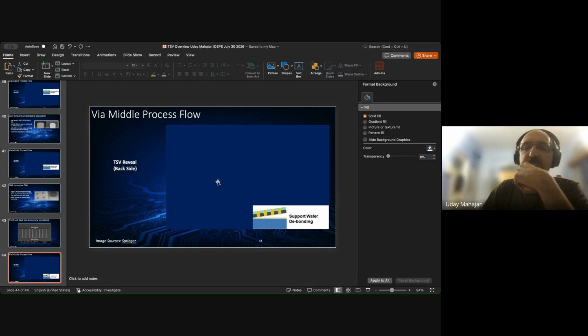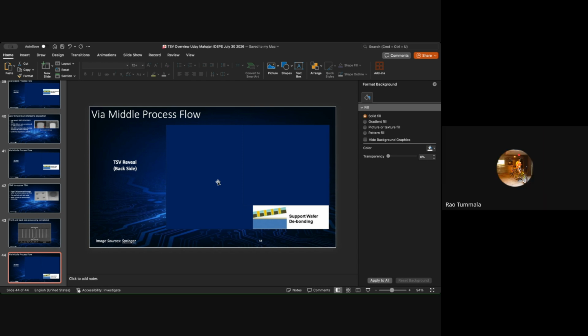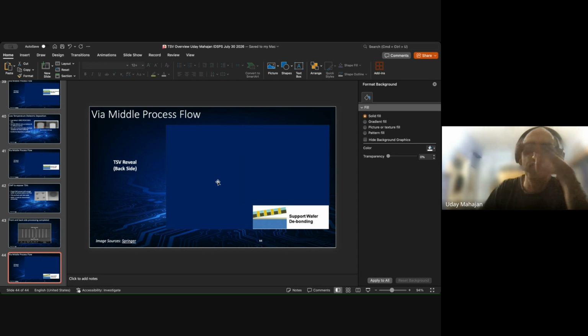Well, 1 micron itself will be pretty challenging. But as advanced packaging becomes critical to keeping the device performance roadmap going, we will have to migrate to TSVs of that order of magnitude of dimensions. And processes like this ruthenium deposition will become key, because there is no way PVD can work at a 1 to 20 aspect ratio. It'll just pinch off the top, and you will not get any coverage at the bottom of the trench or the sidewalls.